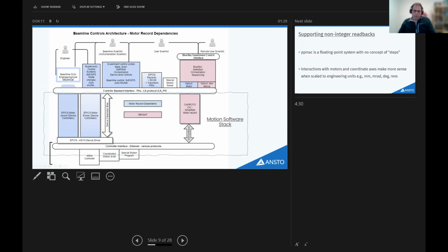So this is a block diagram, as I understand, of all of the main systems that we do, and the two main interfaces. The most important one is what we call the EPICS interface, or the controls standard interface with PVs, and the one down there is the controller interface, which in this case is an Ethernet interface, SSH interface, and everything in between.